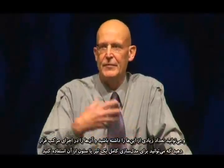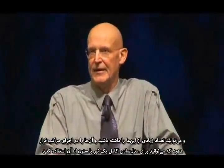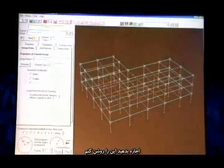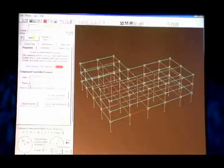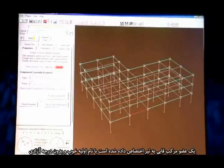Then you can take a number of these and put them into a compound component, which you can use to model a complete beam or a complete column. And then what you also do is assign them to elements. Let me just illustrate that while I'm here. If you look at properties here, if I look at this particular beam, it's been assigned a frame member compound component, and the name of it is perimeter girder with no releases.